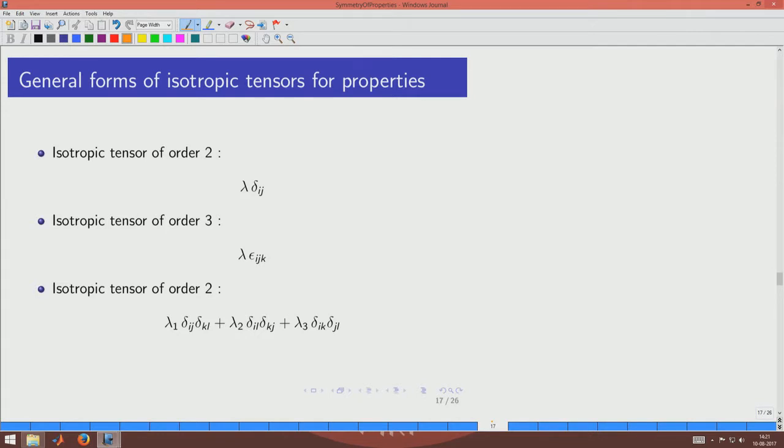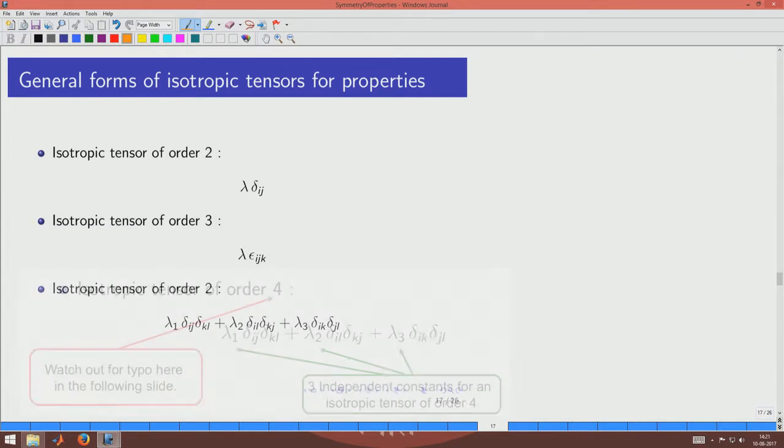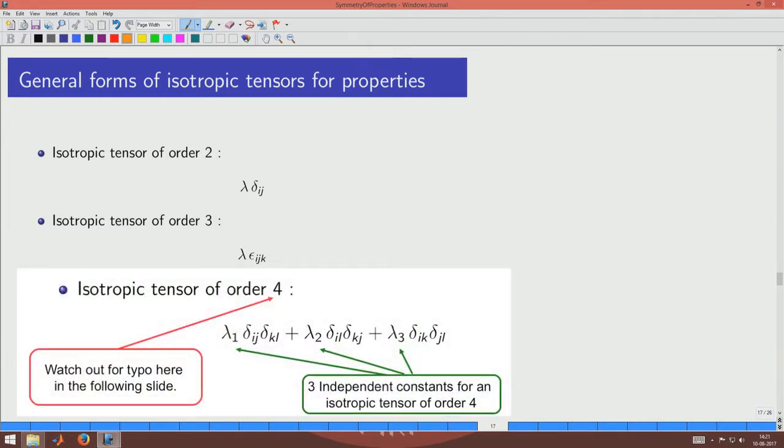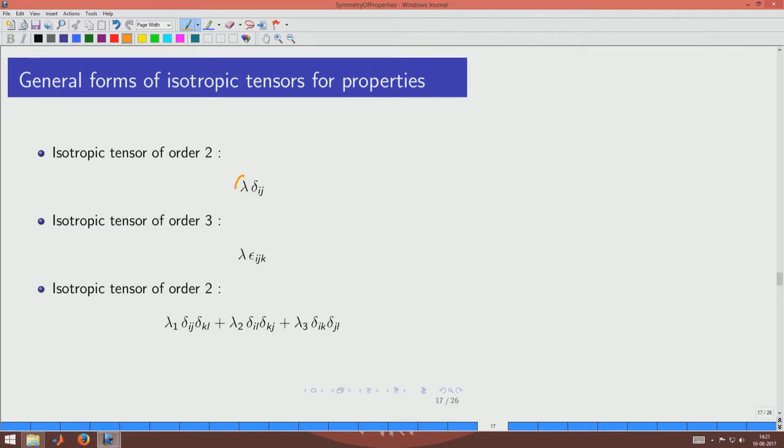Whenever we have isotropic materials like gases, liquids and polycrystalline materials, if you have a second order tensor quantity that has to be represented, then you use only one number, and you multiply it with the Kronecker delta, which is an isotropic tensor of order 2, and then you are done with that. So, if you are talking about the thermal conductivity of a liquid, then you could write it in this manner.